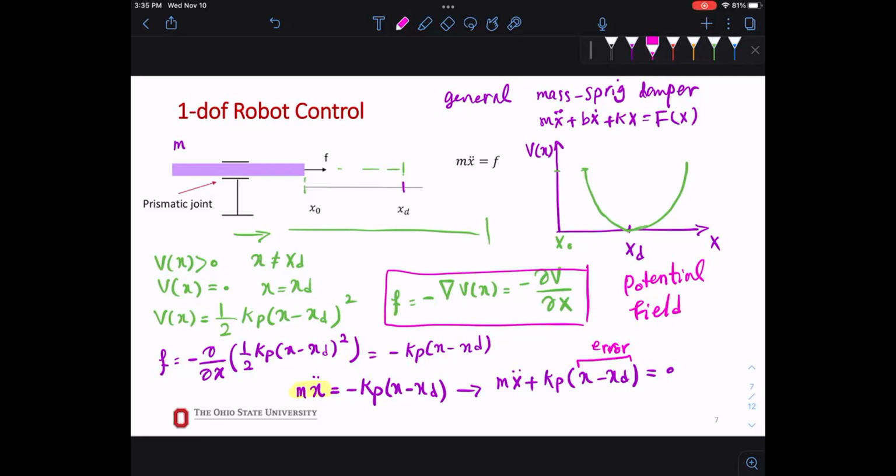So you have the P controller, and this is the dynamic of your system. Now if you want to solve, you can easily solve this. Use ODE45, and you can see the behavior of your system, whether it is controlled or not. It's not. You'll see that you might have overshoot because you keep going back and forth, right? If it's not properly tuned. So this is your position gain for P. All right, so now how to fix this?